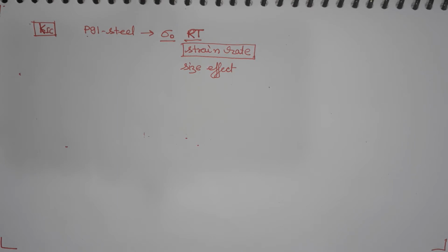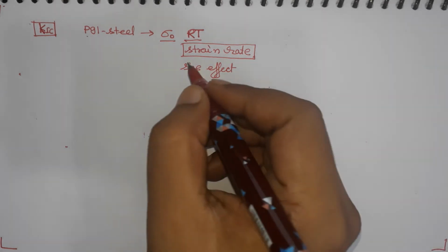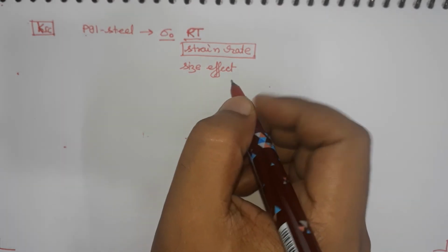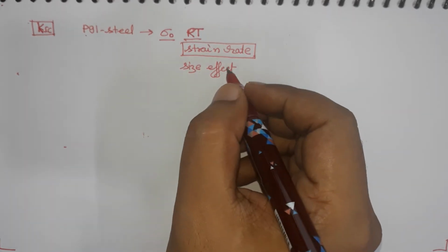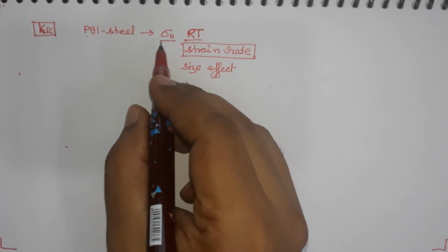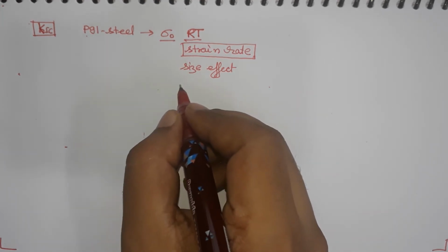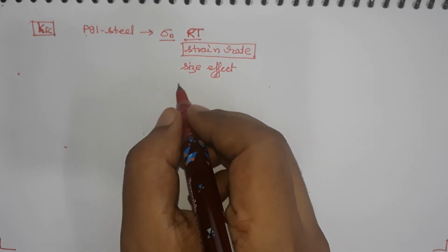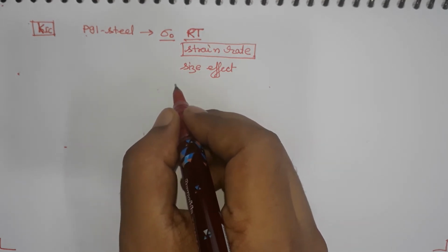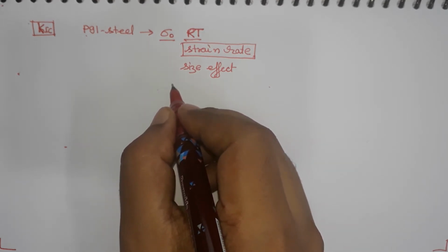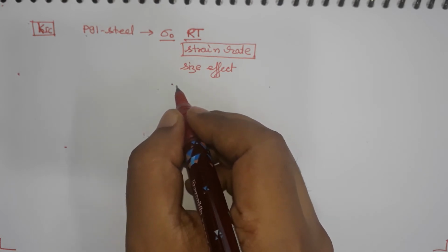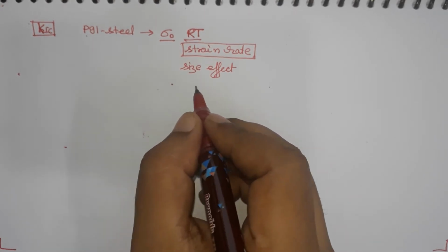So, for instance, in micrometer size, if you are making a specimen, then of course, that material property will be different, especially in brittle materials it happens. Like for example, if you test the yield strength or flexural strength, which is the strength in bending, for graphite for example, and you do that testing in situ in the electron microscopy.